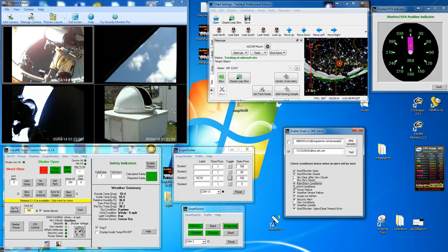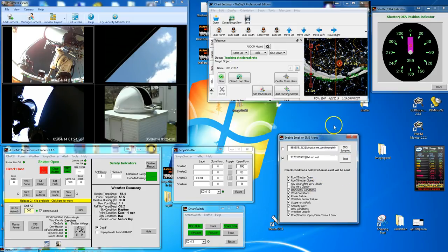Other things such as to alert you, hey, it's time to go observing again. It'll send me a text message if I want when the sky goes clear after being cloudy, or maybe if the weather sensor fails, it'll phone home, let me know that's happening. Power failure: AstroMC, the main rotation boards, have a plug that if you apply voltage to it, if it loses voltage there, it'll scramble the dome. Remember, the dome, we recommend, is running on batteries, and even though the AC power may go out, it still has the capability to at least shut the shutter down, which is the most important part. And all the time keeping you alert through either email or through your text messages on the phone. That's a nice little feature buried in AstroMC that is just another one of the little freebies that's included.